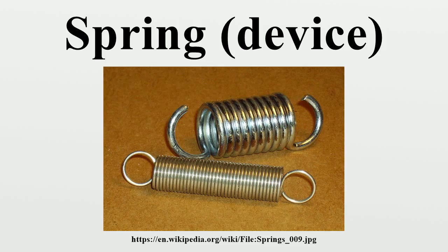They can also be classified based on their shape. Coil spring. This type is made of a coil or helix of wire. Flat spring. This type is made of a flat or conical-shaped piece of metal. Machined spring. This type of spring is manufactured by machining bar stock with a lathe or milling operation rather than coiling wire. Since it is machined, the spring may incorporate features in addition to the elastic element. Machined springs can be made in the typical load cases of compression, extension, torsion, etc. Serpentine spring, a zigzag of thick wire, often used in modern upholstery and furniture.